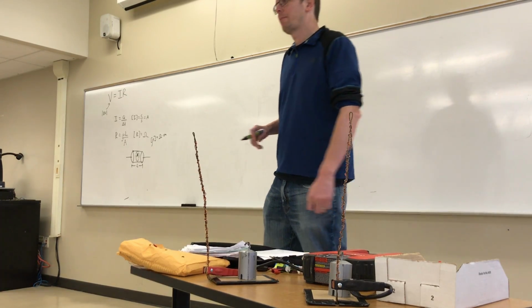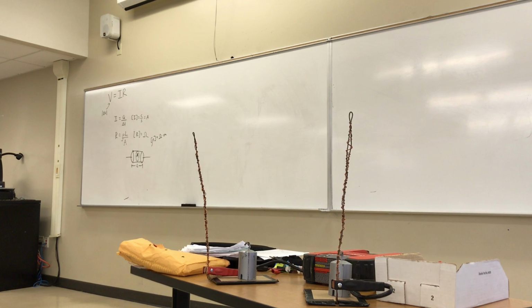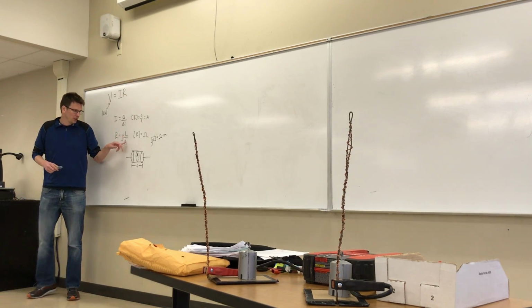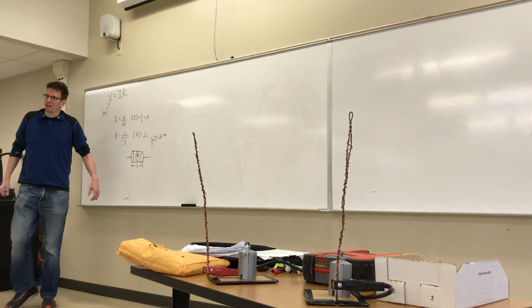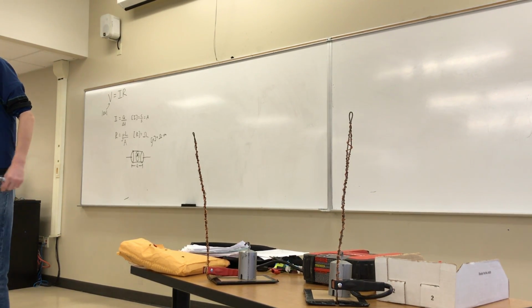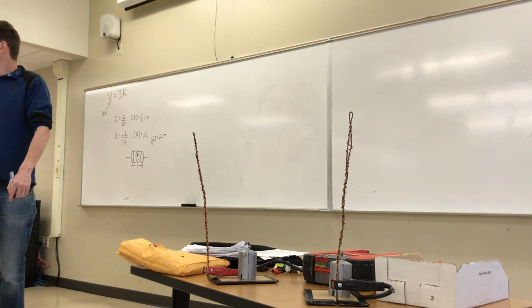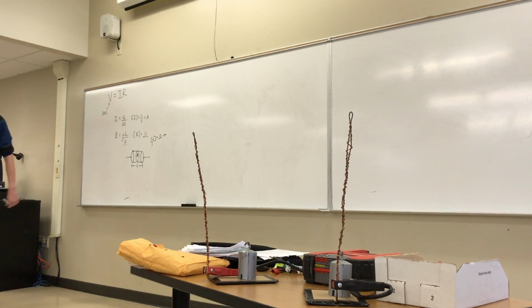So that's the inherent property of the material that informs how resistive or not resistive something is, and oftentimes that factor is far more important than the physical dimensions. If you're talking about resistors, chances are they're about this long, not about this long, okay? And if you're talking cross-sectional area, it's not like this huge. But the resistivities can vary by gigantic orders of magnitude. And so you can have something that is far, far, far longer than something else, but still lower resistance because of what it's made out of.